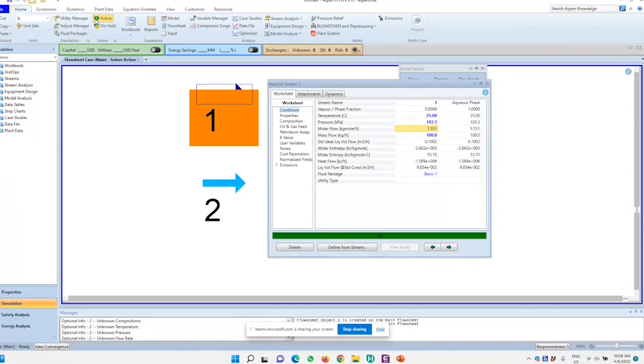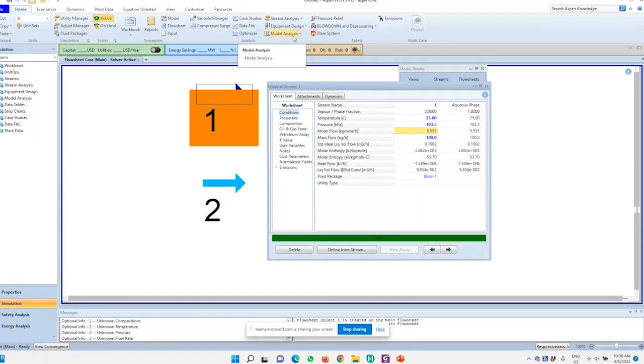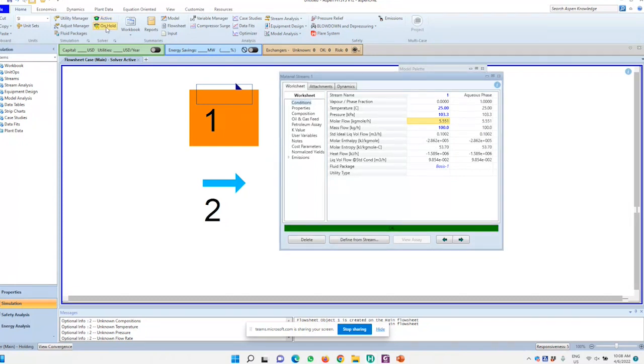This is a very useful hack in case you have a lot of things that you want to change, and you don't want HYSYS to keep updating every time you change anything, because it will take a very long time sometimes if your stream is very complicated. So we just put on hold, change everything. Once it's completed, only then activate the solver. So that's what happens here. Okay, so we have gotten the physical property that we want from HYSYS.